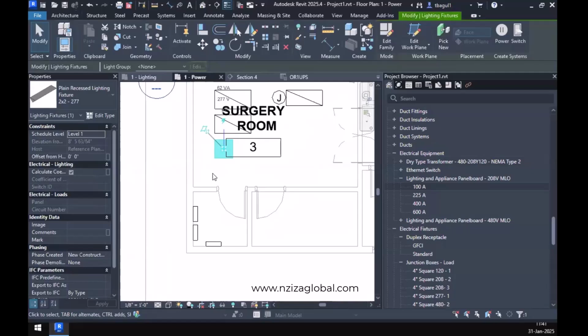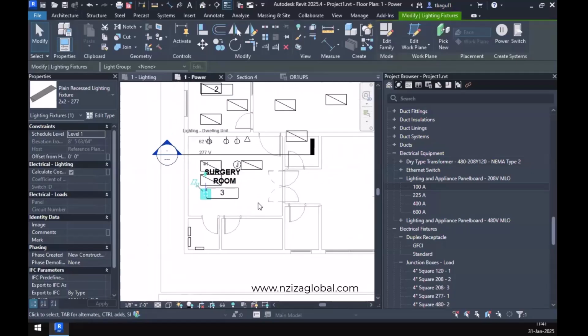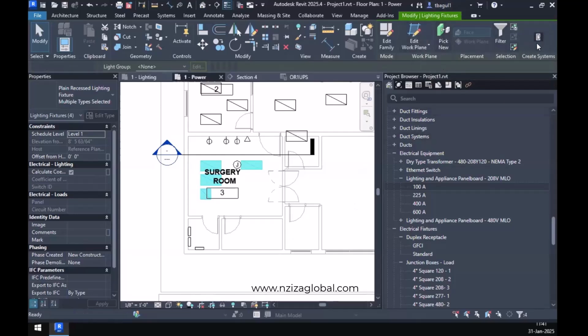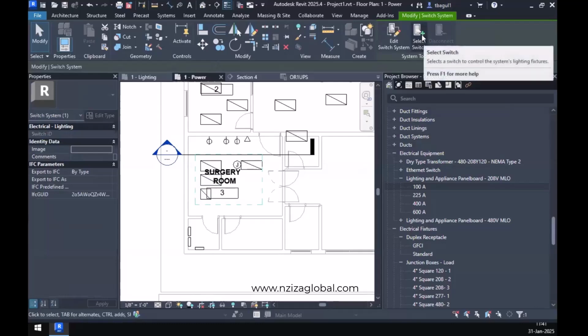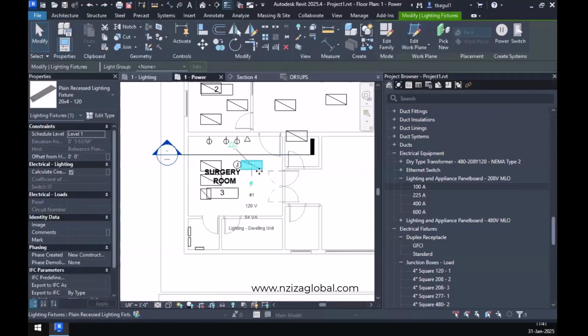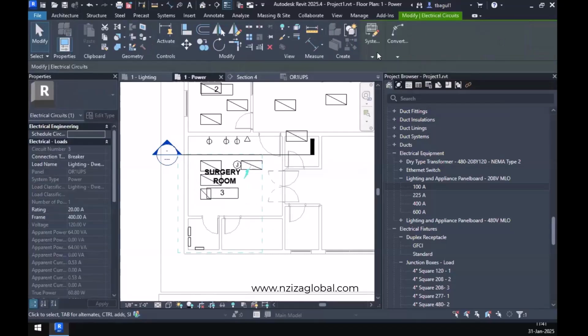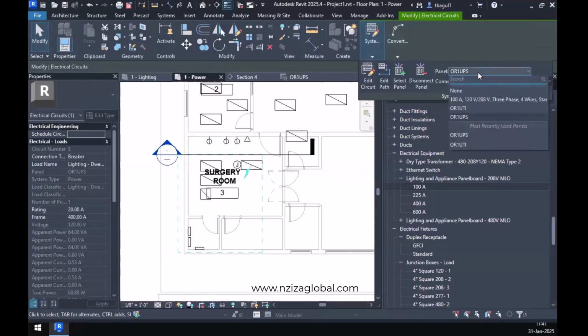Lights also require power, right? So let's say the 4 or 5 light fixtures that we have in the given project. I select all of them, and then we can go to power. Grid systems. No. Let me take that back. Select one of the light fixtures. Same power will show up. And over here in the systems load, you can drop down the box and try to select which panel to select, circuit. All right. Again, all of the light fixtures in the operating rooms need to be circuited to UPS.